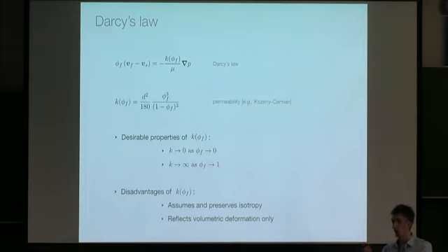And the permeability diverges as the porosity goes to 1, which helps prevent your deformation from driving porosities above 1, which is also something that you don't want. Because in principle, nothing about the equations that I just showed you prevents that. P is the pressure in the fluid. Yes, that's an important point. So P is the pressure in the fluid. I'm not going to talk about a pressure in the solid, and I'll explain why in a moment.